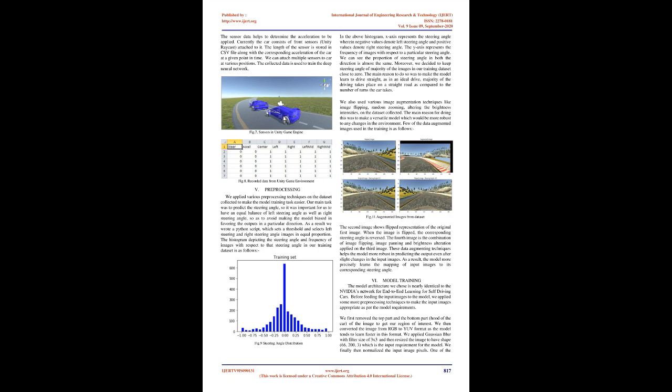In order to collect the dataset, we manually drive the car in the training mode. In training mode, the simulator captures the images from the 3 front cameras and stores them in a database. The corresponding human action pertaining to every frame is also captured by the simulator, which is stored in an Excel file. As a result, the dataset required to train a neural network model is collected, wherein the input to the model will be the input frame image and the output will be the steering angle.